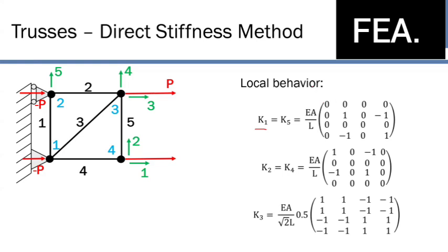So this row, we have two nodes. We have this one and we have this one. Or you can call it U1, U2. I'll call this U and I'll call this V. So U1 is U's displacement in each direction. We go as follows: U in the first degree of freedom, U second degree of freedom, V in the first degree of freedom, V in the second degree of freedom, and so on.